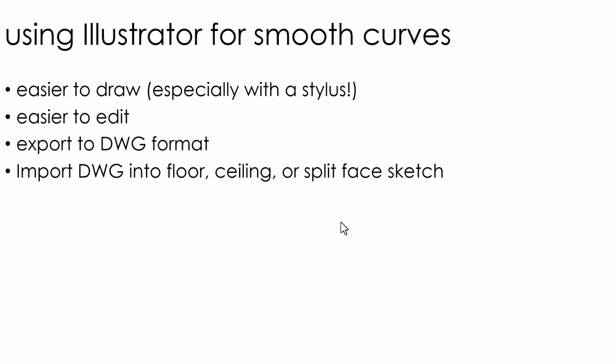You can go into Illustrator and trace it, or you can even use image trace. That gets you the vector lines. Then create a split face in your Revit project, and when you're in that sketch, you can literally go to the insert menu and find your AutoCAD file, and boom, it will trace your lines and turn them into outlines. So a great option for that sort of stuff.